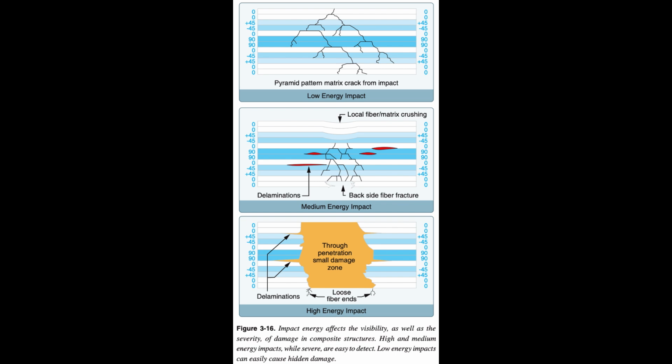As a result, composite aircraft often have specific recommendations on allowable paint colors. If the aircraft is repainted, these recommendations must be followed. Heat damage can also occur due to a fire. Even a quickly extinguished small brake fire can damage bottom wing skins, composite landing gear legs, or wheel pants.